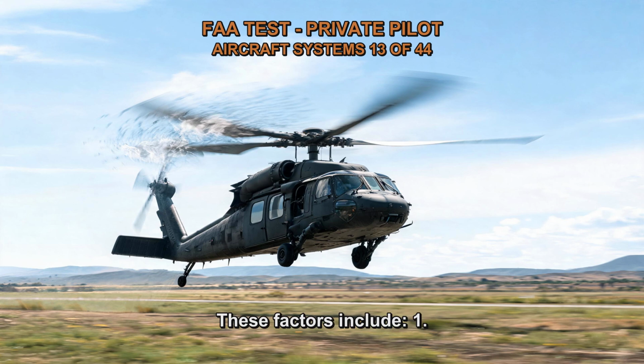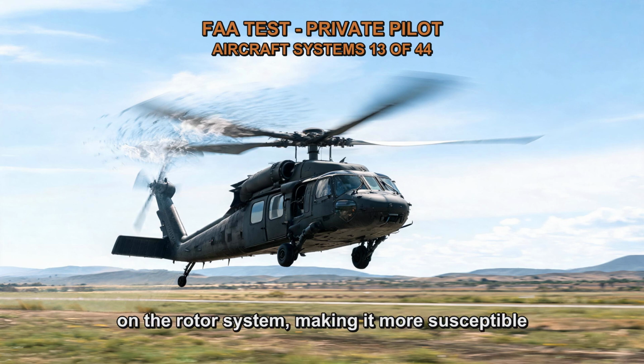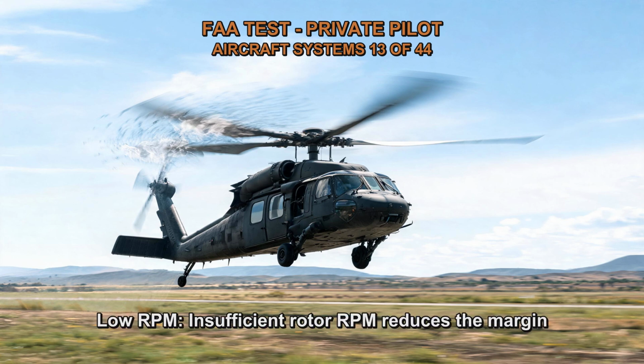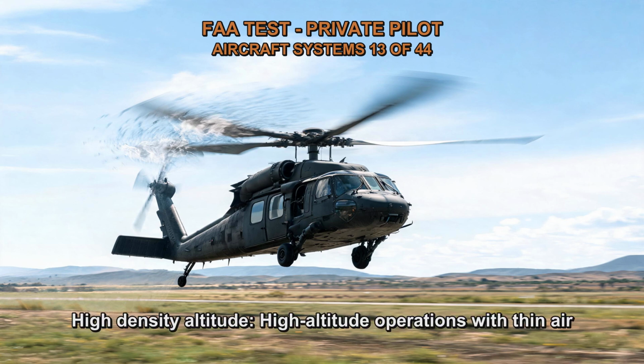These factors include 1. High gross weight. Increased weight places greater demands on the rotor system, making it more susceptible to stall. 2. Low RPM. Insufficient rotor RPM reduces the margin of safety and increases the risk of stall. 3. High-density altitude.